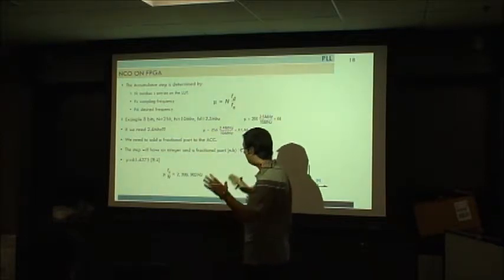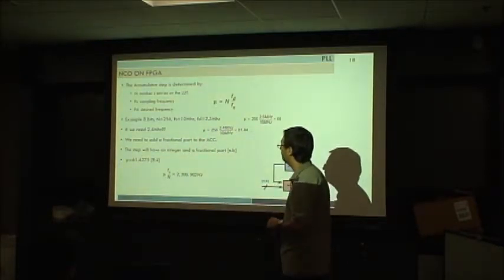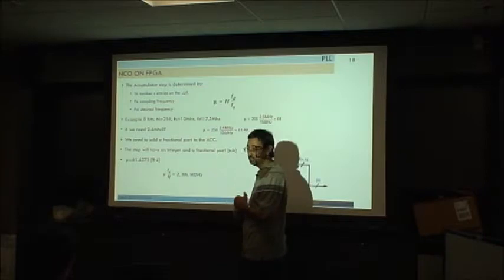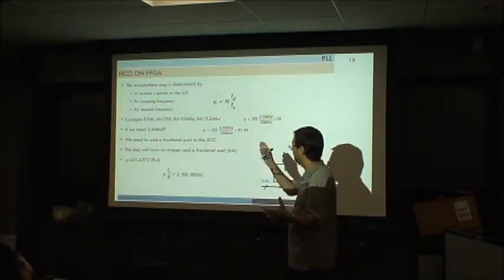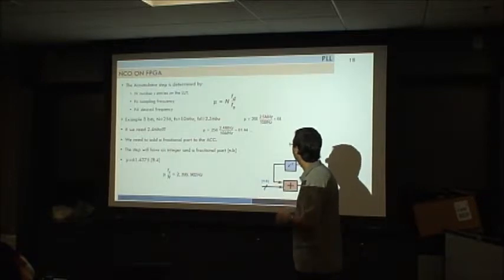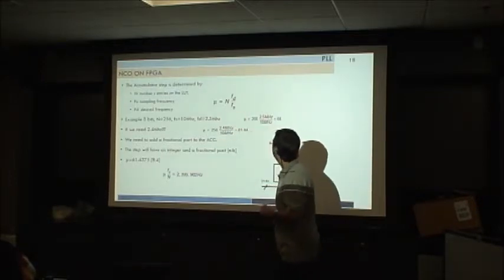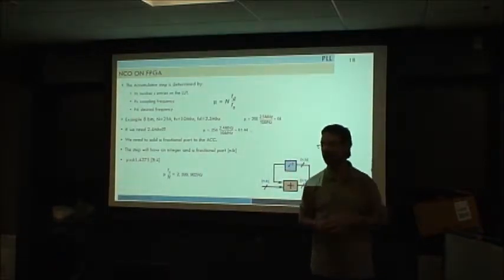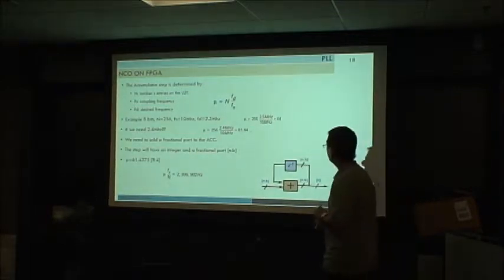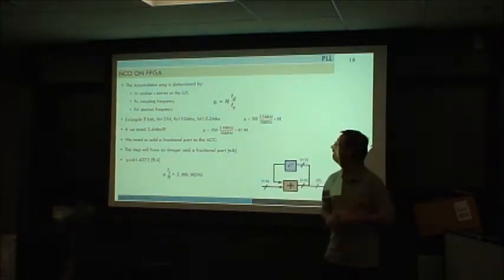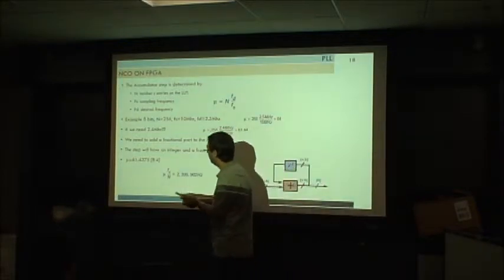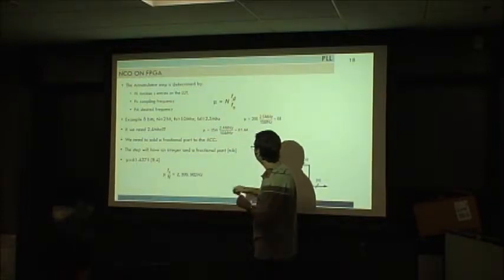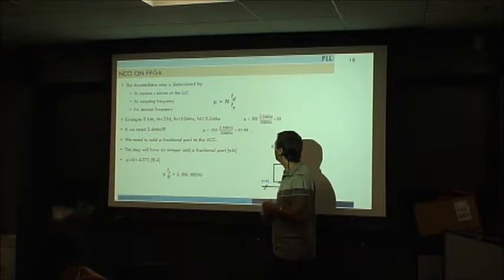For example, you have 8 bits, L is equal to 8. So 2 up to 8, you have 256, and you have a sampling frequency of 10, and you want to create 2.5. You just replace that value there, and here's the result. So this mu value, if I just want to create one fixed frequency, should be 64. Great. But what happens if I want to create 2.4? I do the same math here, but this value tells me that it is 61.4.